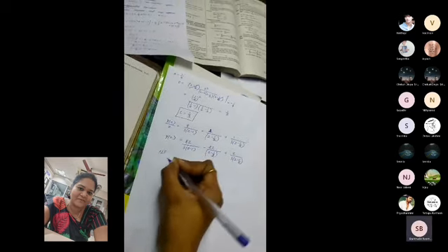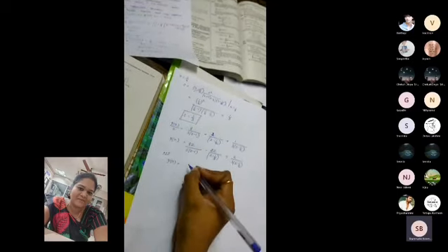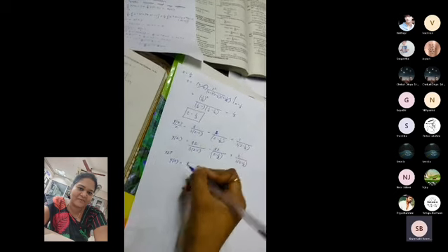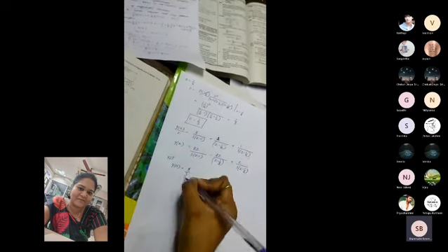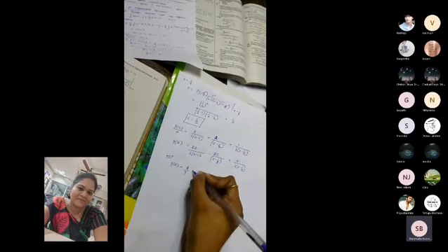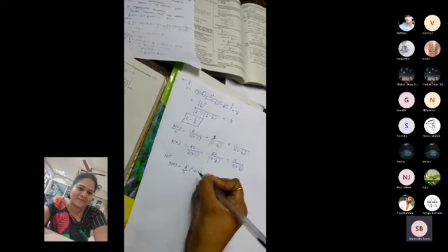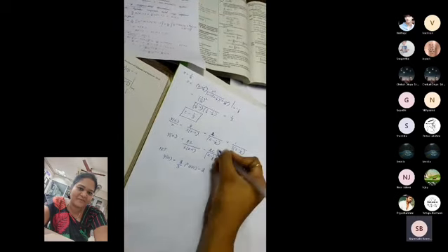Next, you should take the inverse z transform. If you're taking inverse z transform, y of z will become y of n. Then constant, write that constant term as it is. 8 divided by 3, here you have z divided by z minus 1. Here minus 1 is there. So if you're taking inverse transform, it will become 1 power n into u of n, minus 2.